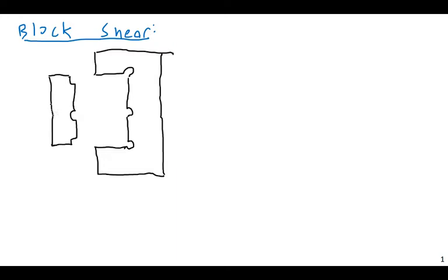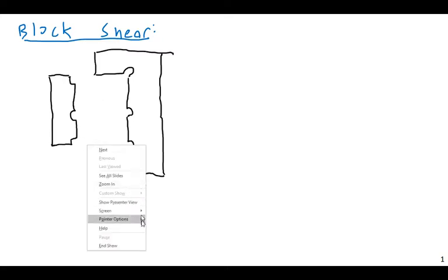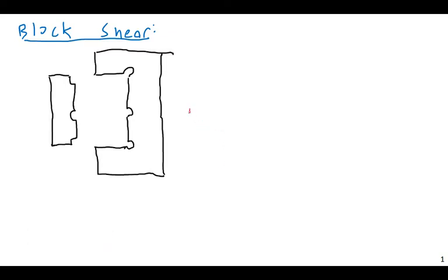So if I want to tear this chunk of this plate out of this plate, and it could be a plate or it could be a web or a flange, anything connected in tension, let's look at the forces. Let's do a rough free body diagram. Well, I have my actual P force that is pulling this thing apart, P and P. But what's actually pulling this thing apart?